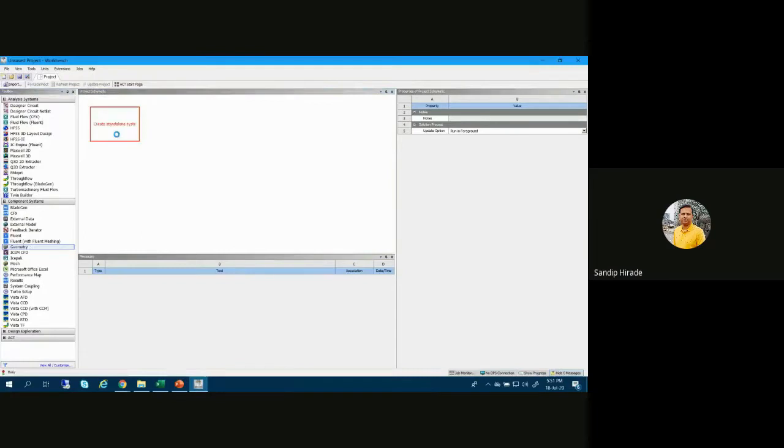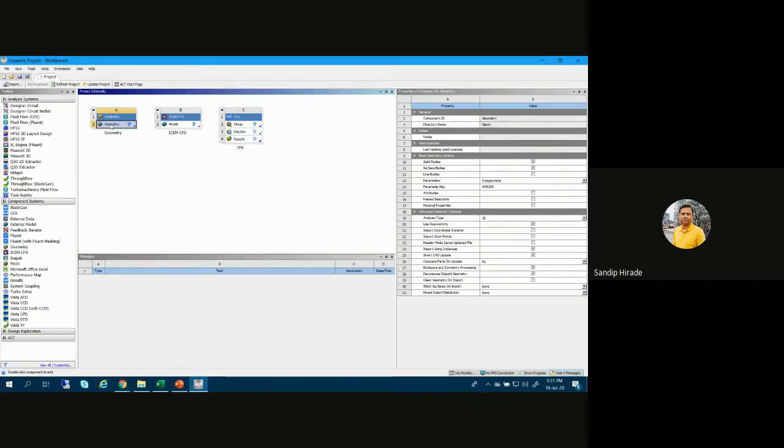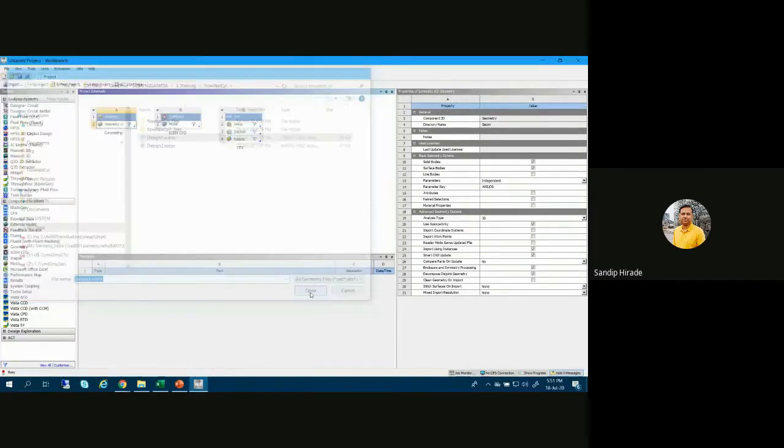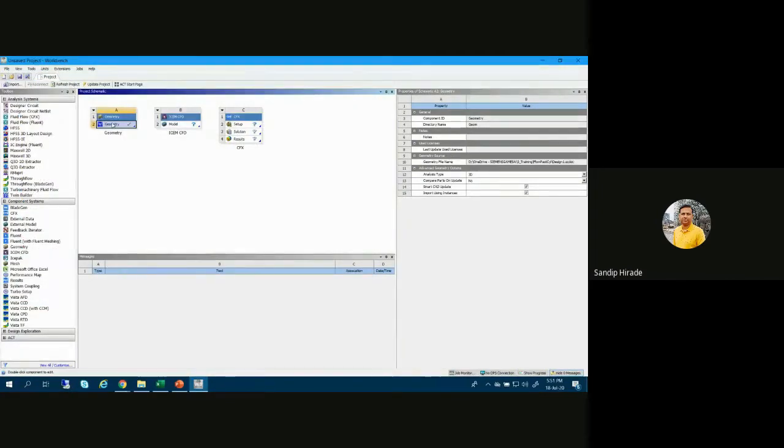So you drag geometry. This geometry has to be meshed. So you drag the ICEM CFD, and once you mesh the model, you can solve it in CFX or in Fluent. Now, once you have a geometry here, either you can import geometry or you can open SpaceClaim here and create your own geometry. So let me import geometry. Okay, so I have geometry. Let's verify it.